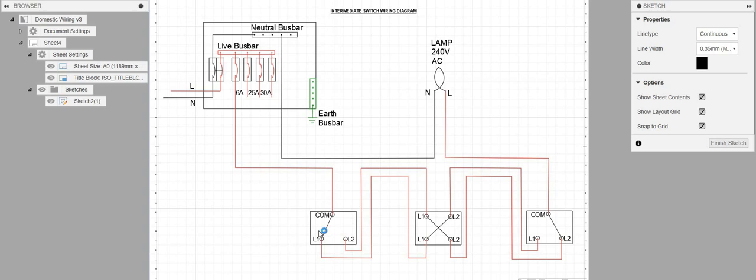For instance, in a staircase, when you are at the lower end of the staircase, the middle part, the landing, and also the upper part. Also in multiple story buildings, you can put one at the ground floor, the second floor, so you can control lighting at different positions. So this is a diagram of the intermediate switch.